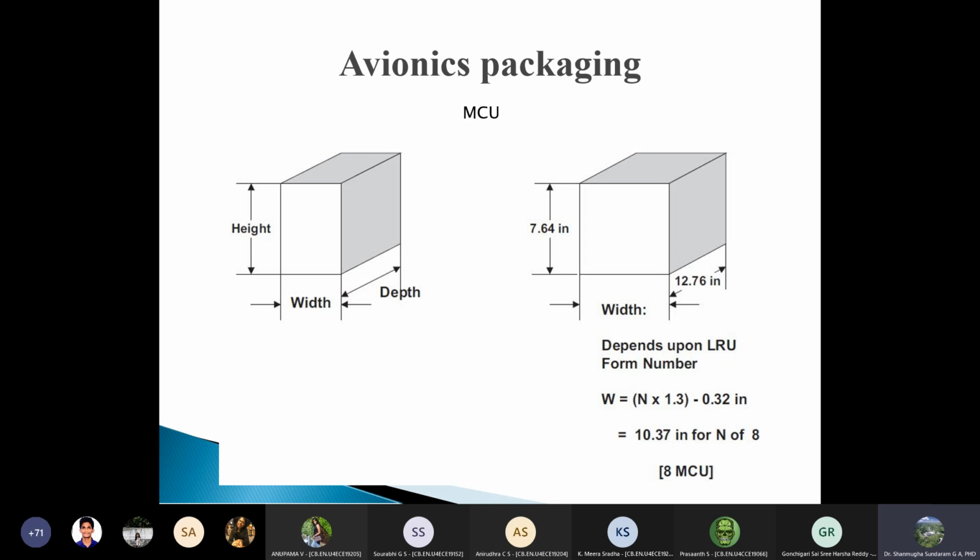Okay, and the PCB has to be designed and deployed considering all of these attributes, and it goes all the way to the actual pin sizes that are identified for each of these connectors, the length of the wiring used, the material for the wires in terms of the dielectrics and the conductors that have to be implemented, and the connectors which are used to terminate each of these wiring solutions. Every one of these is precisely defined so that there is a certain standard that is imposed in the form of the modular concept unit and the larger scaling up of this MCU into the idea of the air transport radio, ATR.